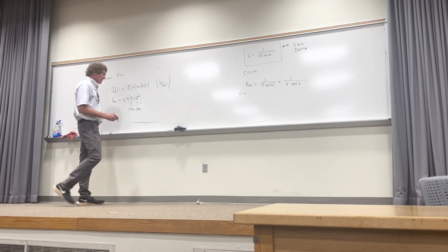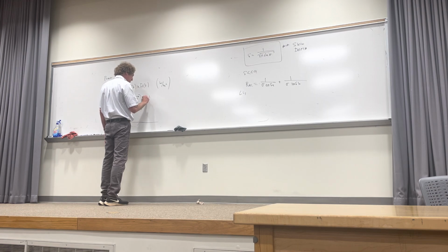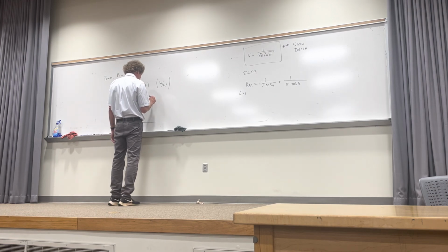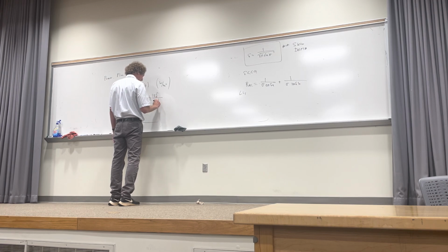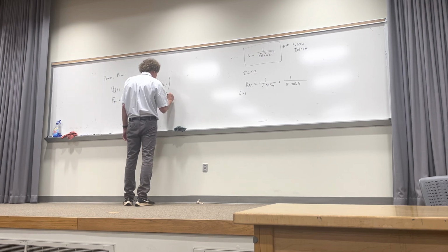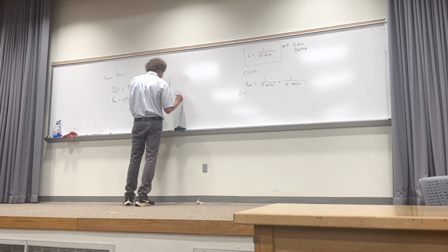If you look at this, this will come down to 1/2, and then it's going to be the magnitude, I'll prove this next time, of the E field squared over the magnitude of the intrinsic impedance of the media times e to the minus 2 alpha z, and there will also be the cosine of the phase angle associated with eta, and this will be propagating in the a_z direction.